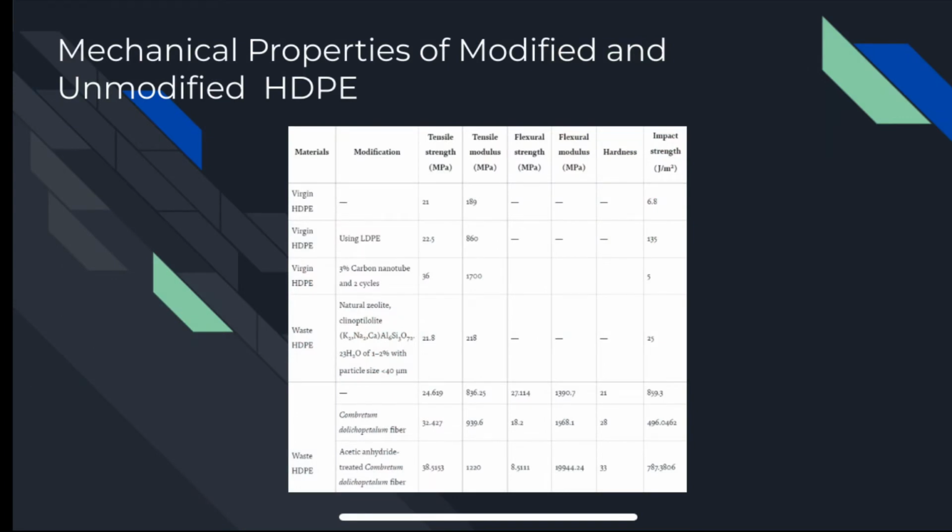Looking at the mechanical properties of the high-density polyethylene, there's a greater improvement in the composite strength due to a mixture of components with compatible types of their size and the particle shapes. The only problem is that it ends up having an inconsistent melting flow rate, and the only way it can actually be stabilized is through a mixture of phosphite and phenolic. Only problem with this is it is actually not economically suitable. But the good thing about it is through this, the enhancements allow increased adhesion, biodegradability, biocompatibility, and non-toxicity to the environment.